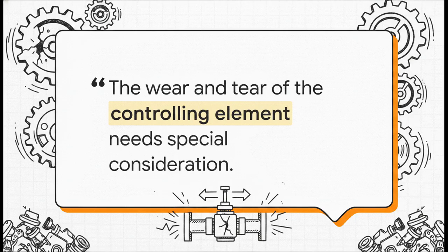I really want to leave you with this stark warning before we wrap up. Picking the wrong mode isn't just an academic mistake. It actively destroys equipment. If you use on-off control on a mechanical valve with tight cycling limits, the rapid chattering, switching violently between full open and full closed, creates severe mechanical stress. If a loop is chattering rapidly, it is quite literally tearing itself apart. You're basically trading a slight upfront cost saving for a massive, expensive maintenance failure down the line.